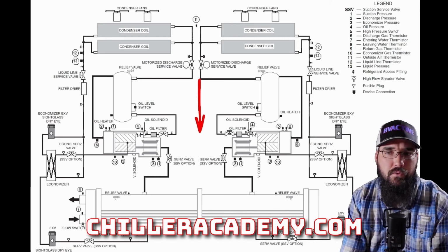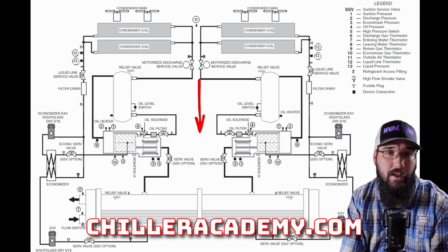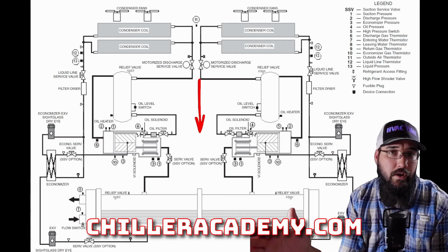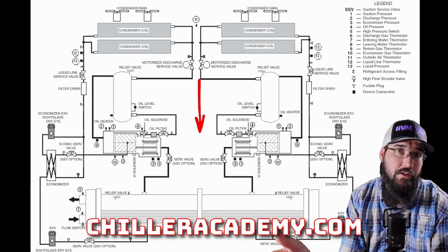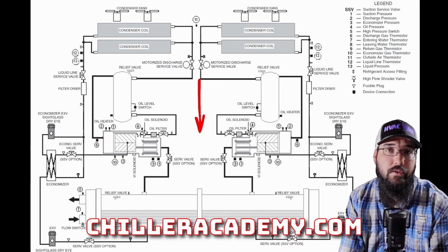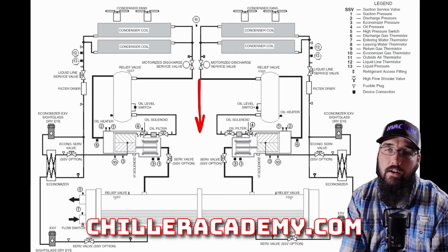So we will do our best to run the minimum amount of compressors possible at all times. And even if that includes one compressor ramping up to almost full capacity to maintain the load, we will do that with that machine, and never even try to bring on a secondary compressor to help it or get the whole evaporator activated.